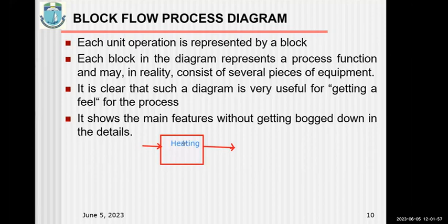And how will you raise the temperature? It may actually involve two different stages, in which you first of all have a heat exchanger there, for example, that will raise the temperature first, or you can have a small separator first before you start putting the heat exchangers. It can also be a series of heat exchangers.